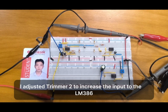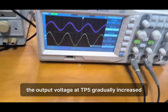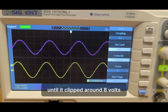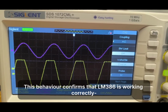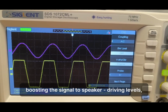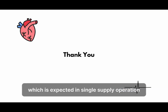I adjusted trimmer 2 to increase the input to the LM386. As the trimmer was turned, the output voltage at TP5 gradually increased until it clipped around 8 volts peak-to-peak, showing the amplifier's maximum output limit. This behavior confirms the LM386 is working correctly, boosting the signal to speaker-driving levels, while clipping occurs when it reaches the supply rail, which is expected in single supply operation.